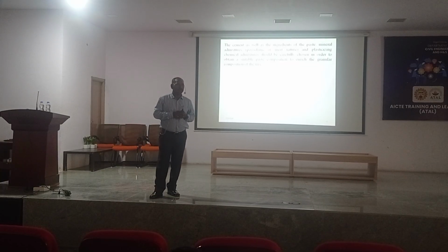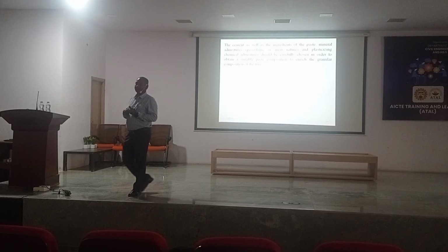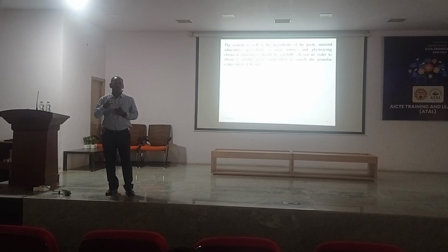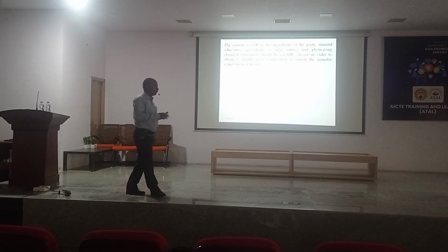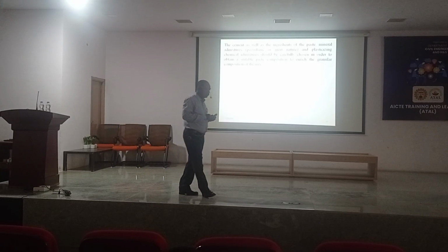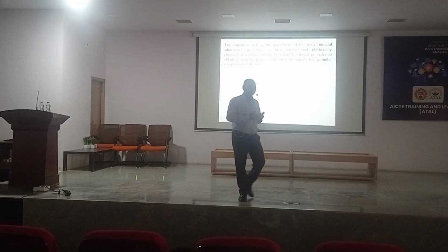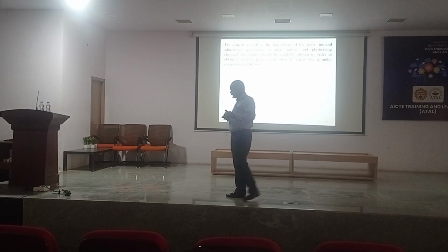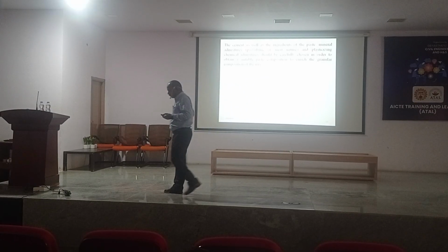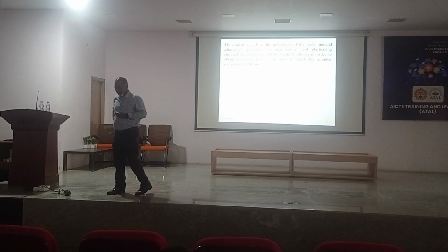More cost. And what is the disadvantage? Okay, I can bear the cost because I have so much money. But what is the disadvantage? If you go for more cement, a shrinkage problem is there. That is the main one. Once you put more cement, after casting you get cracks. Again, you develop cracks. That's why you cannot go for a larger amount of cement to develop self-compacting mortars.